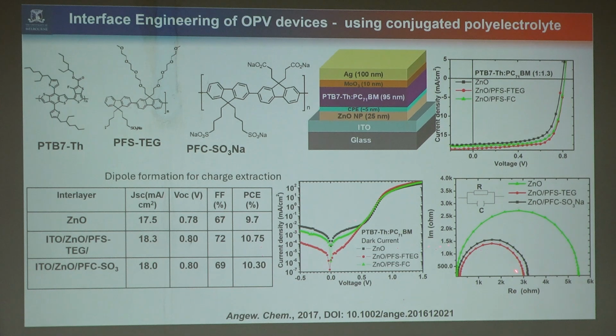It's come from 6K to 3K when you coat on the top of the active layer. So this is one of the evidences that when you have the double interlayer, the series resistance is also greatly reduced. So when you have the double interlayer, not only is the energy level aligning, which improves the electrical resistance, the decrease in electrical resistance.